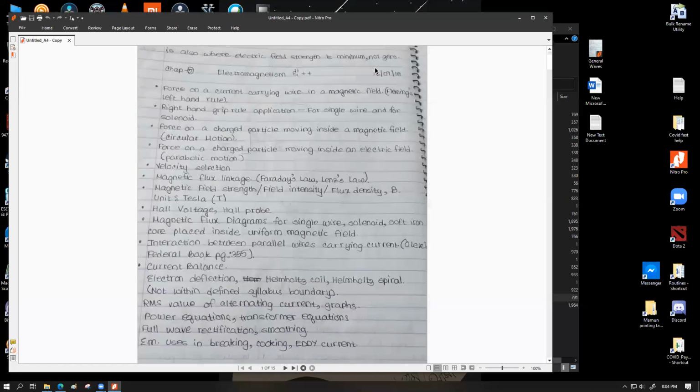The reason is that iron itself can work as both of these materials. It depends upon what are the alloy constituents of the iron that we are using. Typically, higher carbon contents give us more soft magnetic material. For example, cast iron. Cast iron is usually made directly from the blast furnace, which is the furnace that we use to make liquid iron out of the ore. It usually has a lot of carbon content within itself, which can work as a soft magnetic material most commonly.